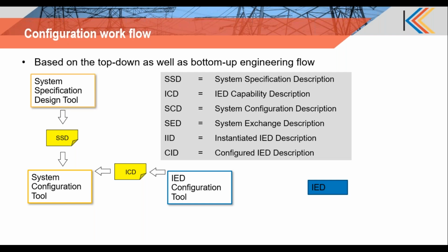It does the instantiations, and it also does all the mappings or binding of each IED functionality to the specific functionality defined in your SSD file. The output of that configuration is something called the SCD file. That is the master configuration file, which contains all your substation model information, as well as the IED data models, the data mapping or data flow between these IEDs, and the communication parameters required for the IEDs. So this SCD is your master configuration file.